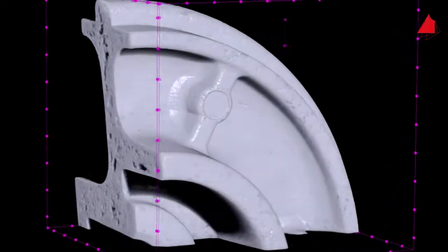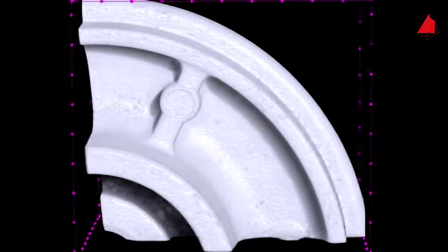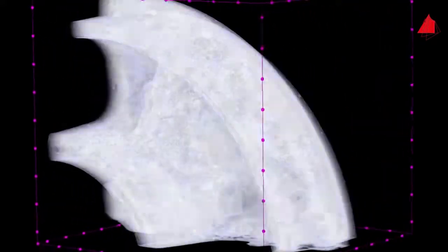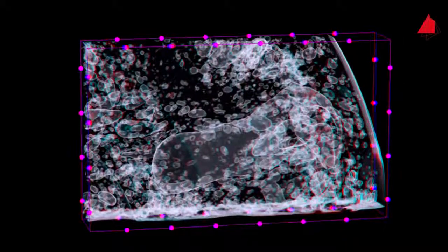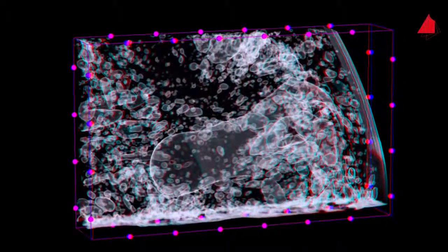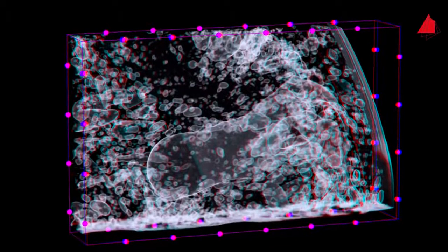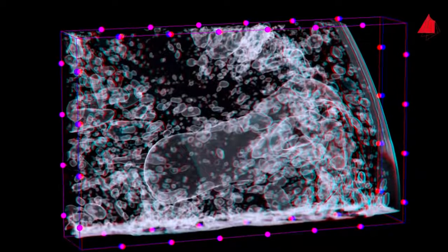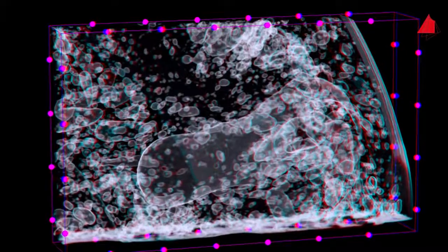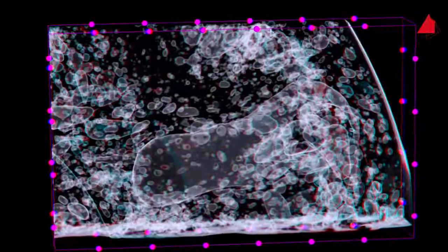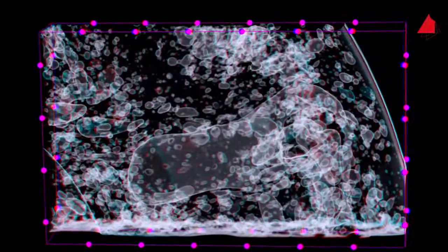If preferred, the material can also be visualized transparently. Then the defect surfaces appear bright. The following image shows an enlarged section of the sample in red-green technology. With ordinary red-green glasses, the pores in the interior of the material can also be experienced in 3D. Computed tomography is a fantastic method, so it is not surprising that it is being used more and more as an excellent non-destructive testing method in materials testing.